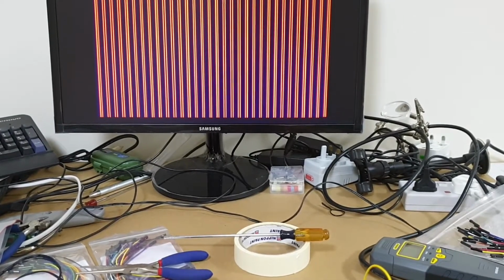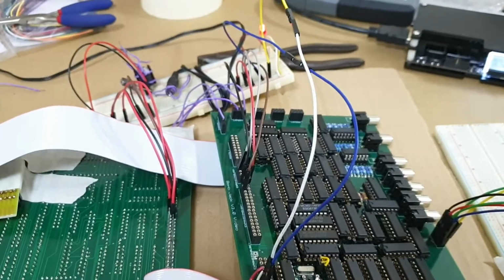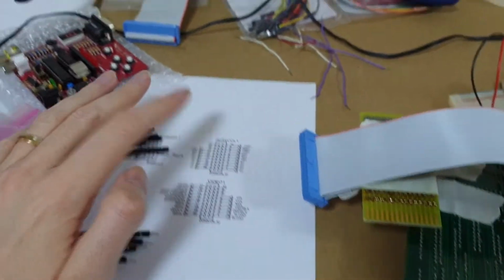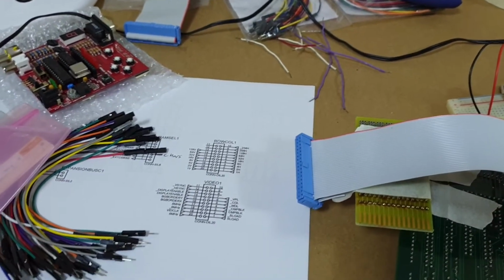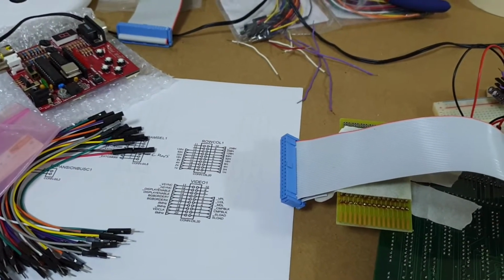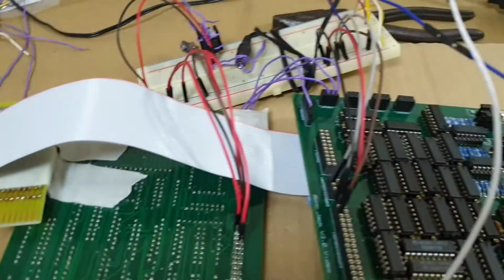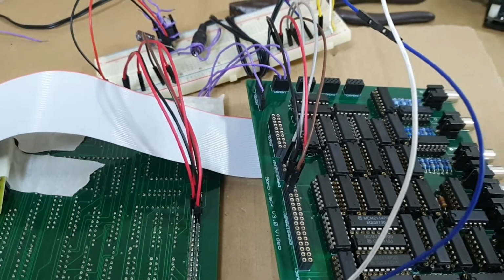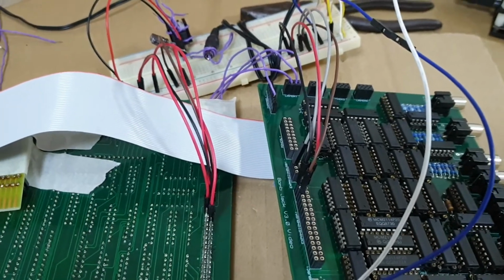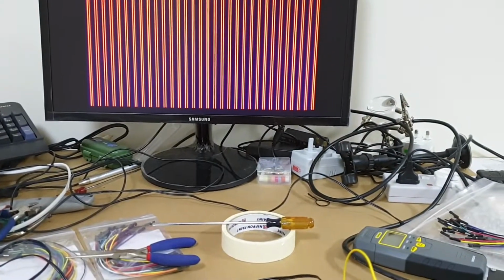Definitely worthy of note. It's a very important piece of information when I'm looking to expand these boards further and I need to consider crosstalk considerations for this row column header. It may also mean that I may want to completely separate this header out, have it on a different place on the board to isolate these signals even further. Interesting. Really good piece of information to know.